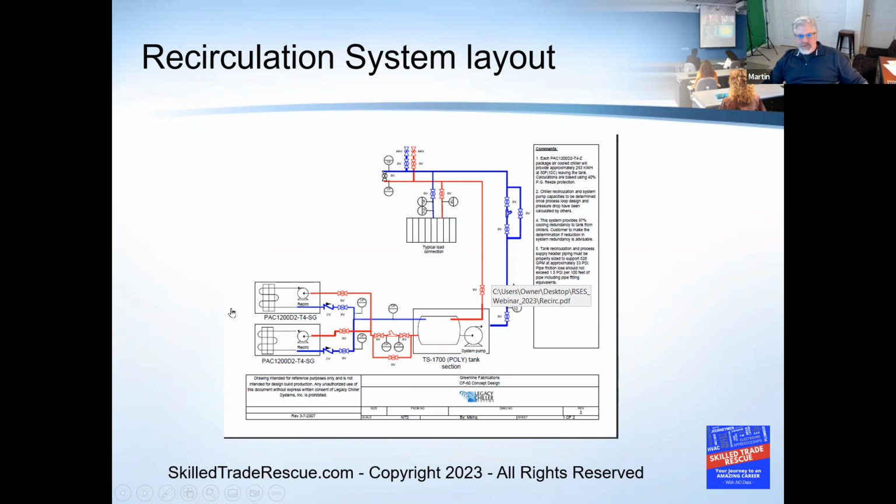All right, so this is the recirc side. This is the system side. All right, so we have our big system pump here. It's pulling off the tank, going out through another bypass assembly, going through here. We always recommend installing a bypass at the end. I'll explain that in a minute. And then it goes back to the tank, right?